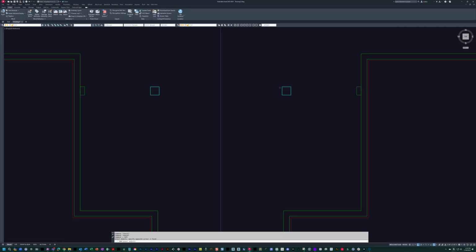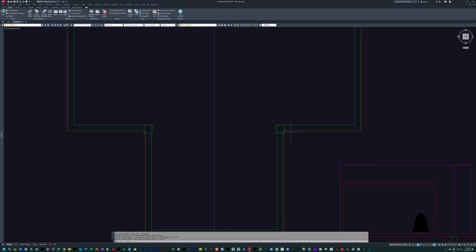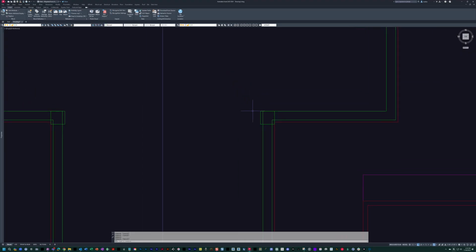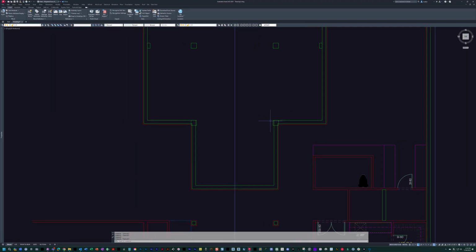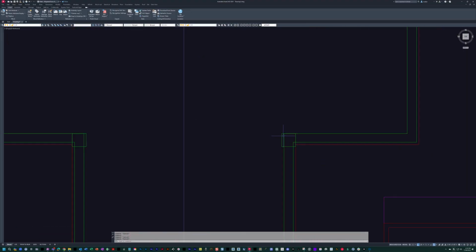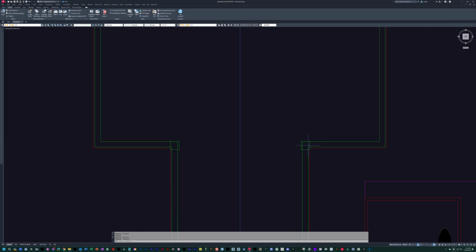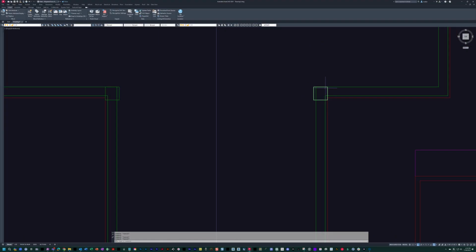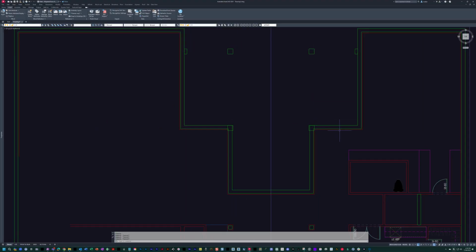Now the other thing we could do, if we want to look at it, which would be kind of fun, if you see, if I copy this down, because this is 8 inch plus 2 inch, that's 10 inches total, and this is 12 inch, technically this creates odd set of alignments that either works in some places and not in others. So one of the fun things we can look at is, okay, do we want to make the column kind of proud on this corner, meaning, you know, we have that nice 2-inch reveal right here, so we can get almost like a pilaster type of idea, and maybe that would be good.